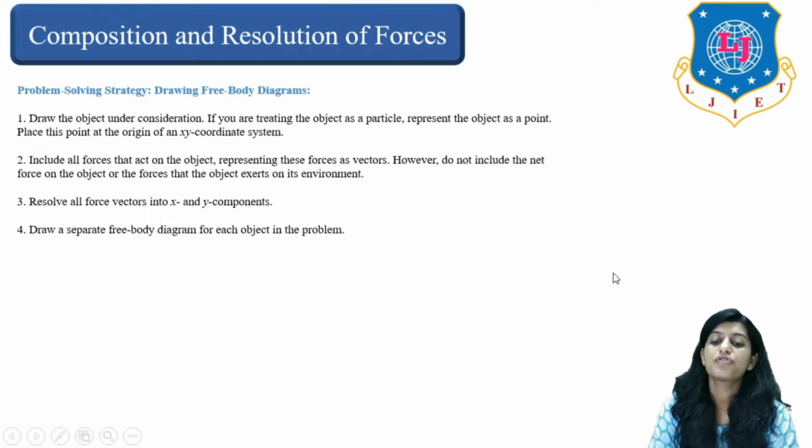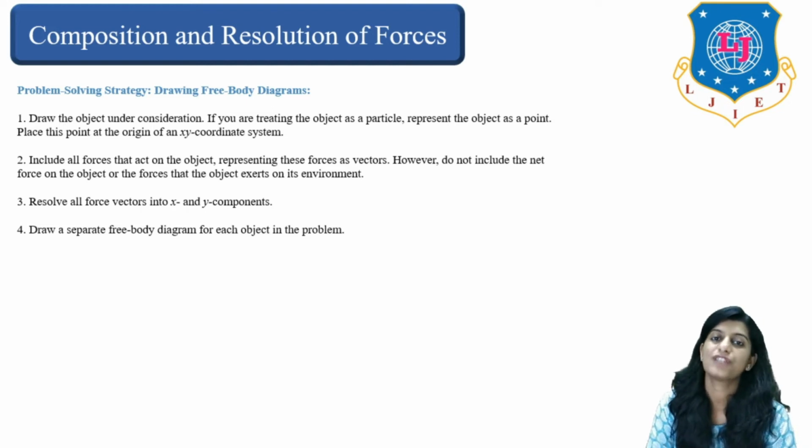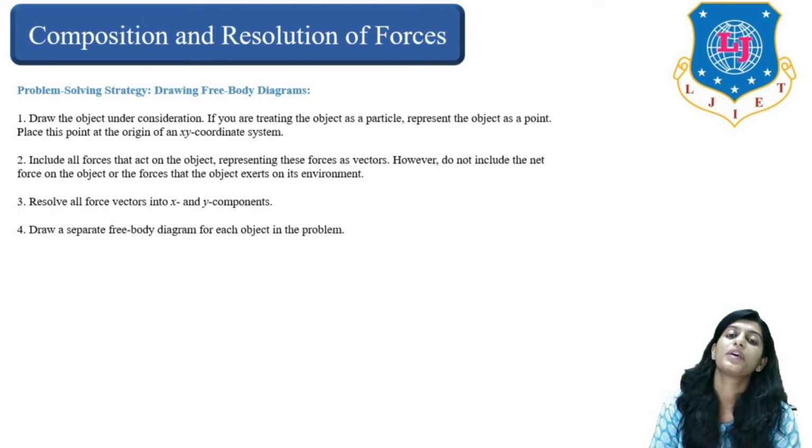Now, how can problem solving strategies be used for free body diagrams, or how can a free body diagram be utilized for problem solving techniques? There are a few points which we must understand and consider. Let us consider the first point: draw the object under consideration. If you are treating the object as a particle, represent the object as a point, right?